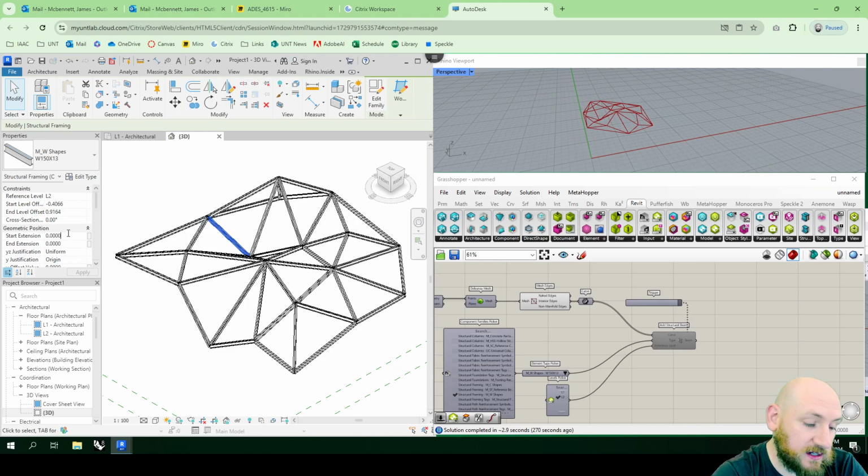The Rhino and Grasshopper method is probably the other way around, where you edit your parameters and then you create them. So it's flipped there. Here we create the beam and then we want to change the extension. Now this is in meters, so I could do minus 0.25 here, and same on the end. I can see that that got slightly shorter.